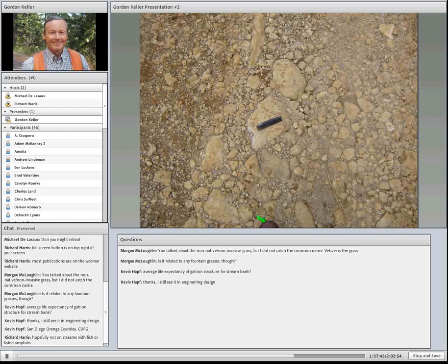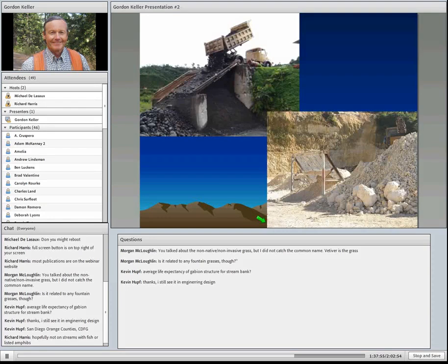What do you do with big coarse rock when you've got just bony cobbles in the road, which are rough to ride on and a pain in the neck to maintain for a road surface? You can screen them out. You can just run your material through a grizzly, something like this, and get rid of that coarse material. Maybe use this coarse rock for riprap someplace, and then put this finer material, say minus down to 2 inches, on the road. Take everything smaller than 2 inches, put that on the road, and you can live with it much better. So it's a pretty inexpensive way to improve pit run material.